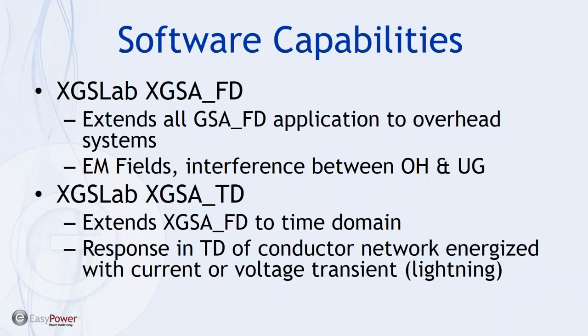You can calculate the effects of lightning and also the fault current distribution due to a lightning strike. So you gain a lot more capabilities with the above ground, and you're getting one step closer to modeling reality, to the point where you can do almost academic level studies and answer very specific questions on your grounding system when you have to worry about above ground facilities.